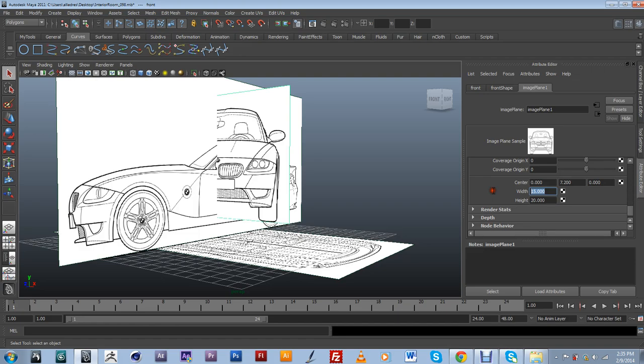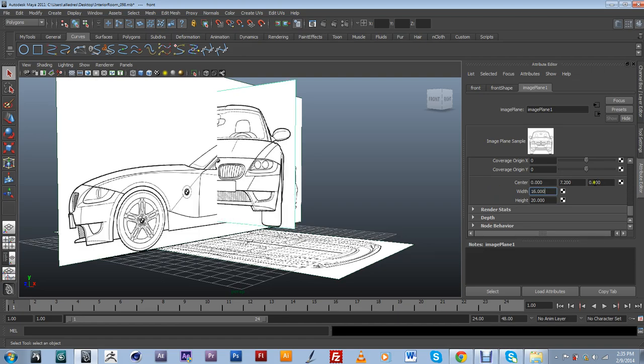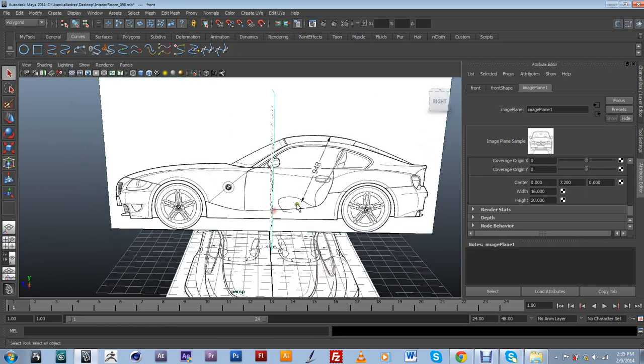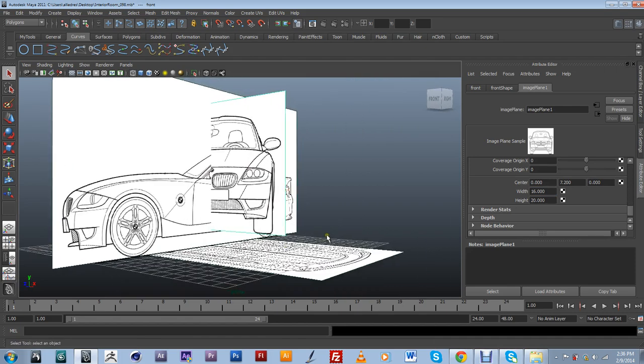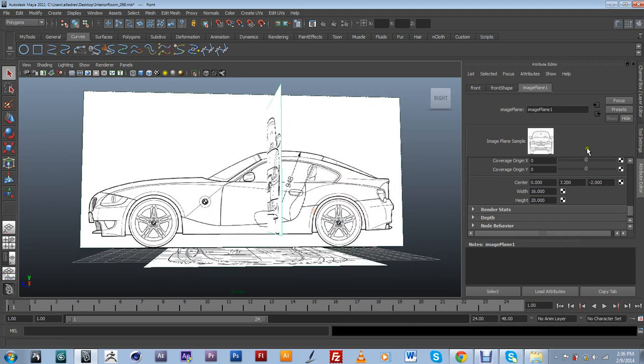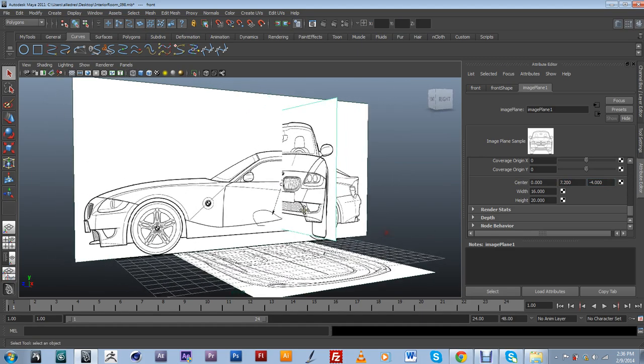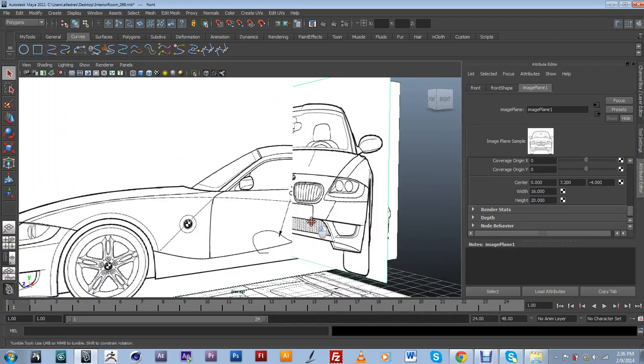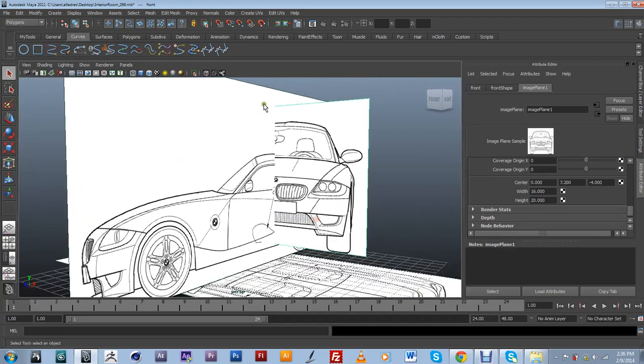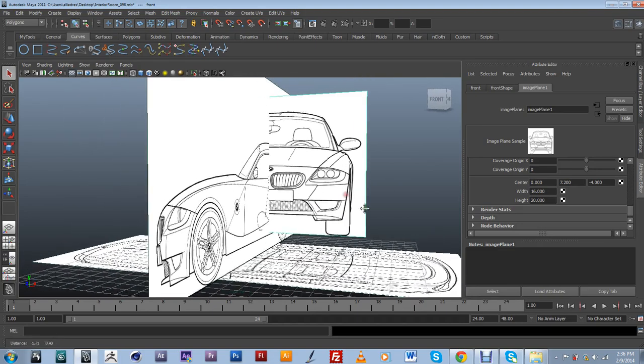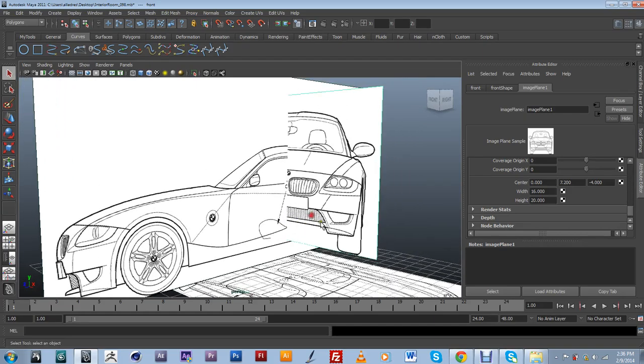and that might be a little bit too much. Let's do 16. And I need to bring it back on my Z-axis and then down, so let's do that. Do like a -2 over here, maybe a little bit more, -4. That seems to be the right point. And again, I'm trying to contrast the highest point on my front and side viewport to make sure that these two are proportional to each other.